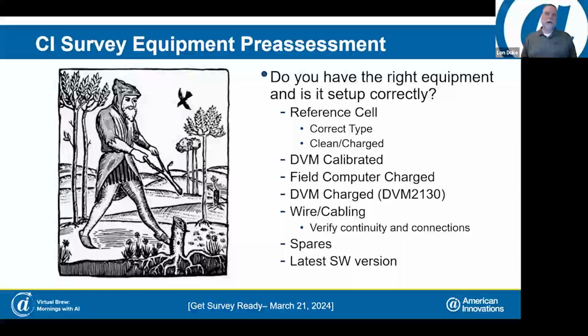Your wire and cabling, it's always a good idea to check those out. Just check them for continuity, make sure there's no frays or anything on them. Do you have any spares? A few spare cables is a good idea.